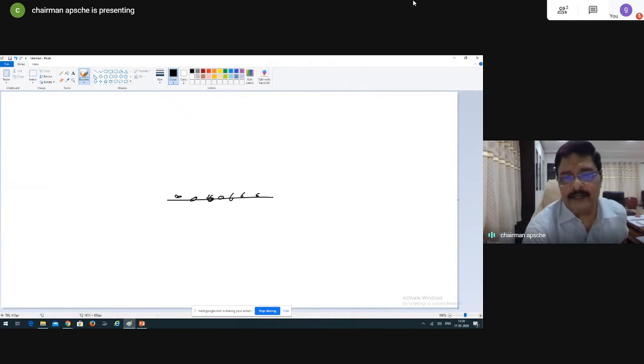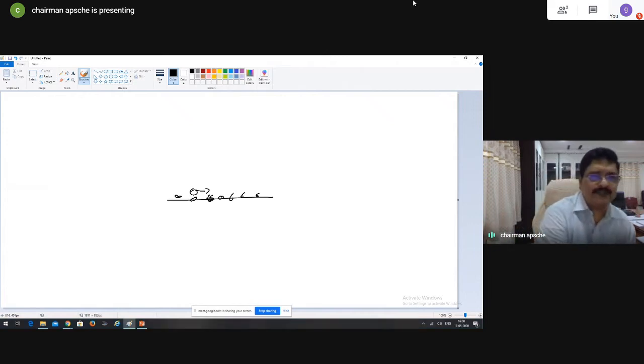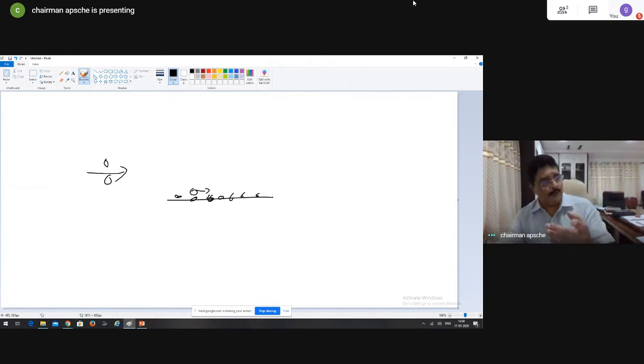Now suddenly the fluid molecule in the next layer wanted to move. It is not experiencing the wall friction, and not a great one, because the molecule has already experienced viscous friction between the molecules in the free stream region also, but that was moving at a free stream velocity u infinity. Whereas the second layer of molecules is now rubbing against a stationary molecule.